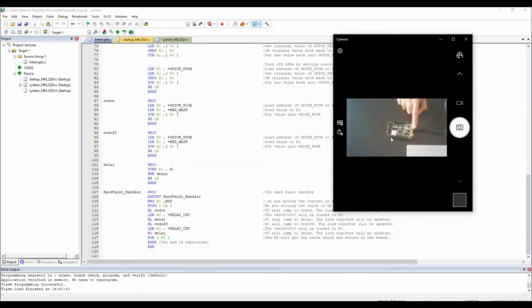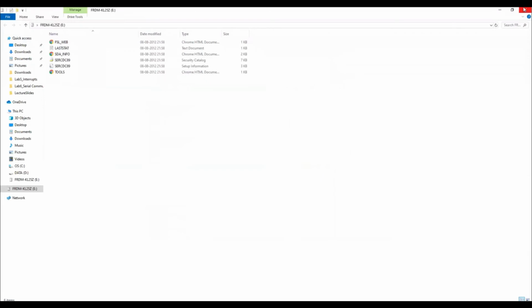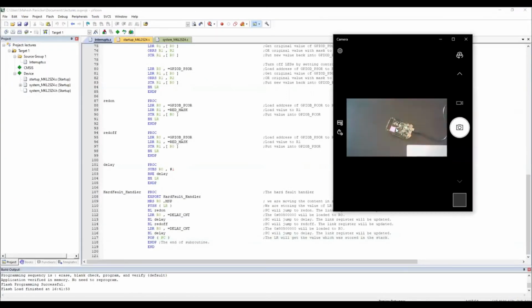And you will see that there's nothing happening. In many cases, there's a reset button right here. If I press that, this will work. But for some reason, some of the boards have some hanging issues. So you have to switch on and switch off the power. So for that reason, I need to plug out the USB. So I'm going to plug out the USB now. Okay. And then plug in back so that you will see the things blinking. So you see it is blinking.